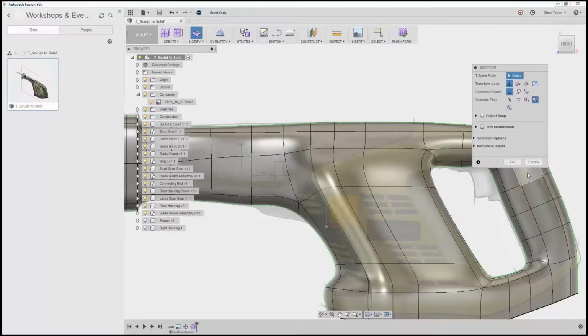And when you're doing these modifications, don't try and do every single edge one after the other. Just jump from one edge to the next, and leave a couple between, and let Fusion do the smoothing over between the two as you're going along. A lot of it's practice, but also paying attention to what happens. So as you're doing it, see what happens, and then modify your approach depending on the results that you want.